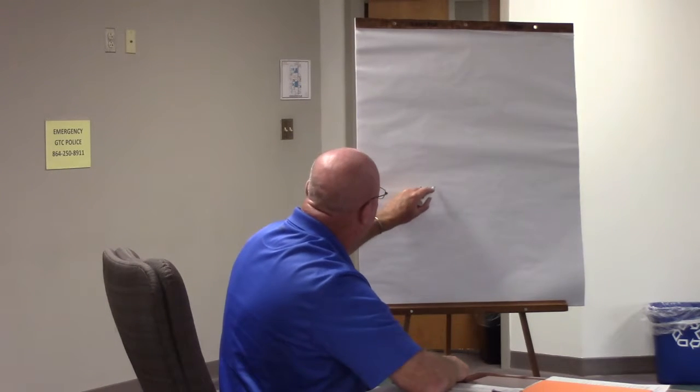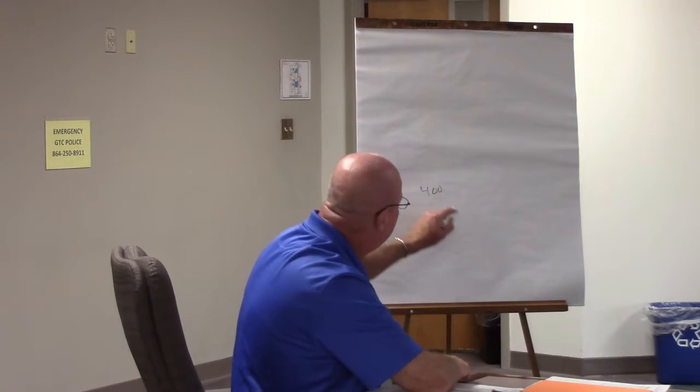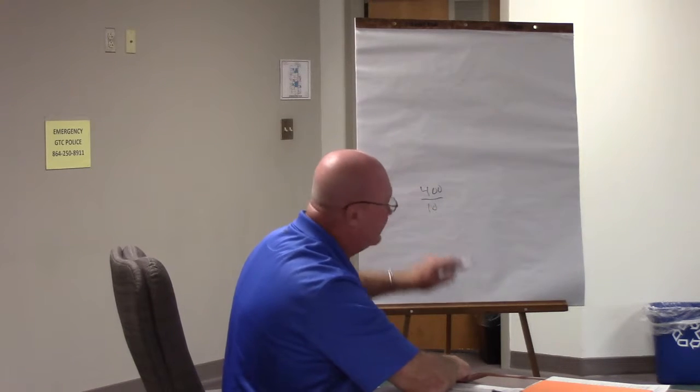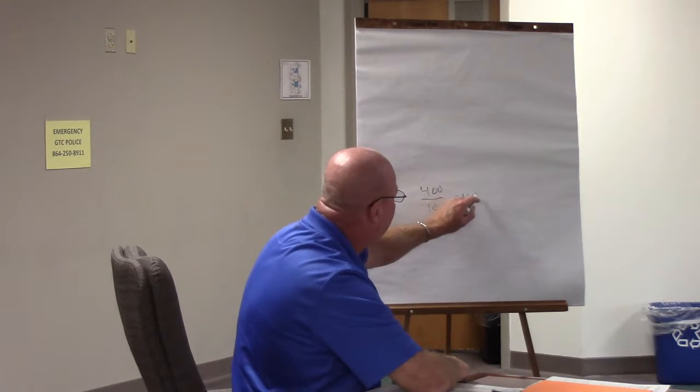For field installation of tap conductors, leave an enclosure or vault in which the tap is made, the ampacity, and they just kind of word it differently, and I kind of like this actually better than 1,000%. It's the same thing, but it's 1/10. In other words, 1/10 is saying, if I had a 400 amp, how much is 1/10 of 400 amps? What would you do to get 1/10 of 400 amps? Divide by 10, right? And that is what, 40, right?